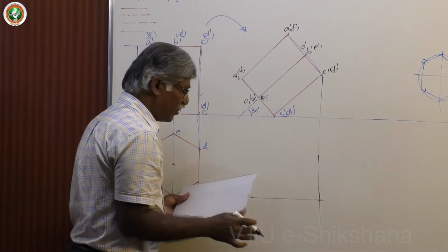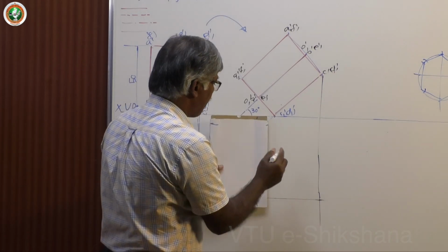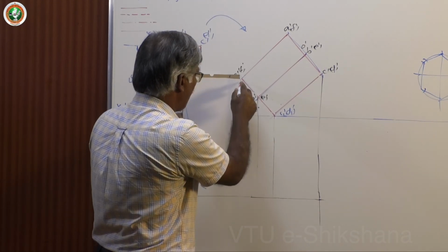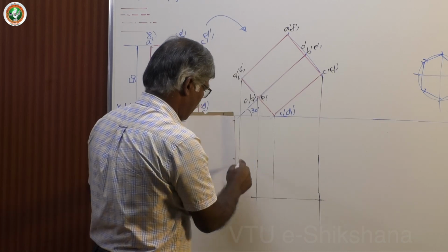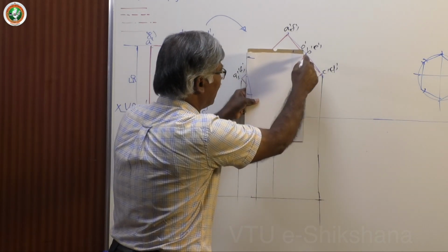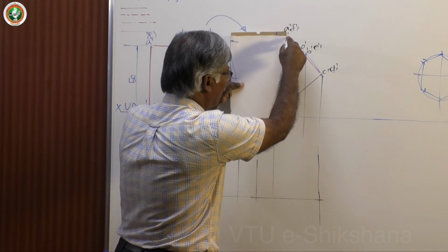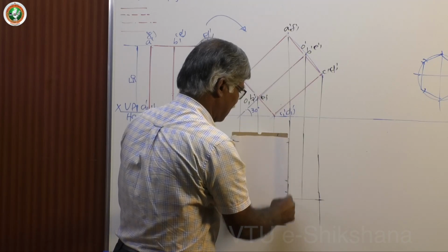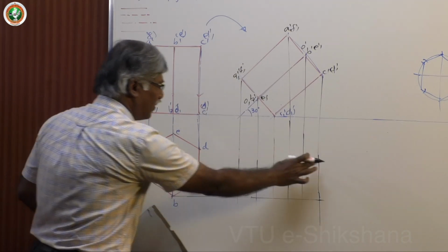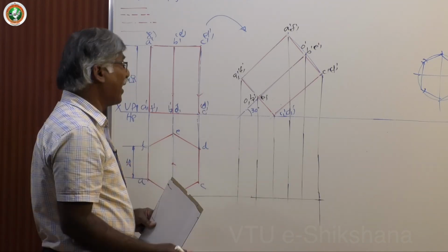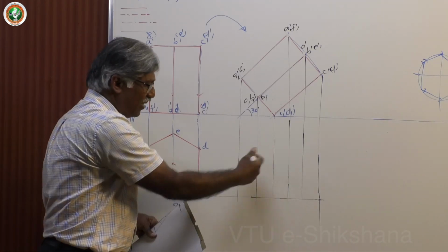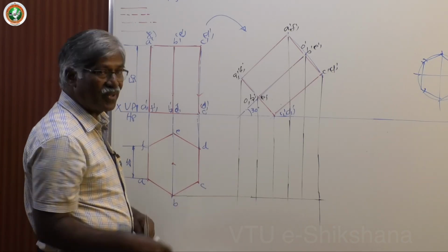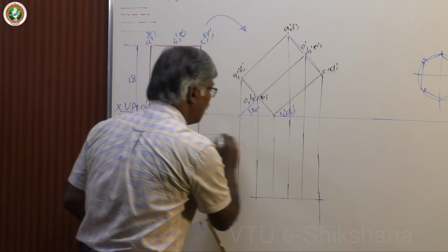Now, draw projections. Get exactly 3 lines for each lamina. We are assuming that the 2 laminae are there, we are projecting it. Yes. This for the base, this for the top face. Sometimes it may overlap, that depends on the angle. So, if it is 30°, it will be very clear, separate laminae. Otherwise, it will be very close or overlap sometimes. Now, draw these lines.